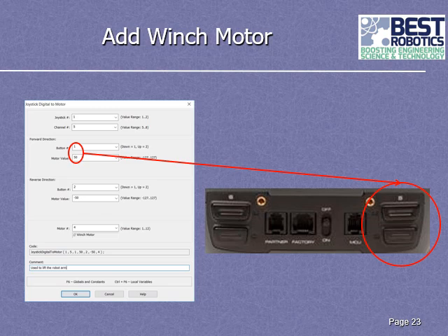Since the range of values that you can put in here is minus 127 to 127, what that's saying is it's going to be moving in the plus direction about a little bit more than a third of the speed with which that motor can go. And this is something you can play with. Once you get it all going and you realize, oh, it's either going too slow or too fast, you can simply double click on that function and change this number to whatever you need it to be. Sometimes you have to play with it a little bit to get the exact right number.